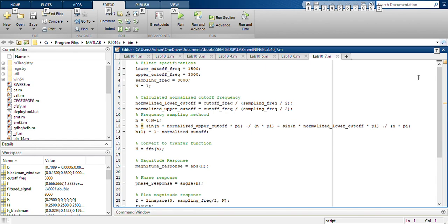The objective of this lab is the implementation of an FIR filter using the frequency sampling method. In this method we are discussing Fourier transform design and Fourier transform phase, discussed in the previous section. Frequency sampling is another alternative. The key feature of frequency sampling is that the filter coefficients can be calculated based on the specified magnitude of the desired filter frequency response, uniformly sampled in the frequency domain. Here it is designed flexibly.